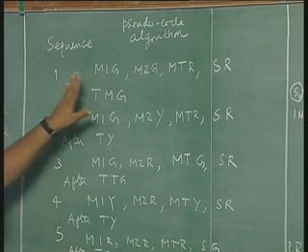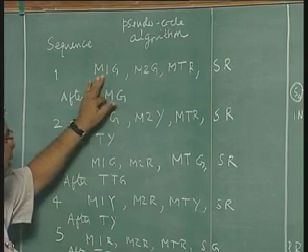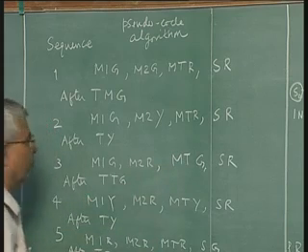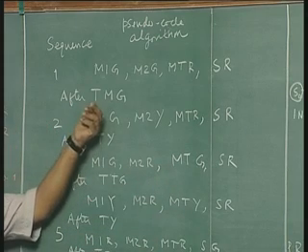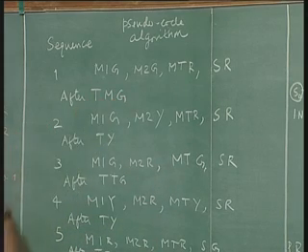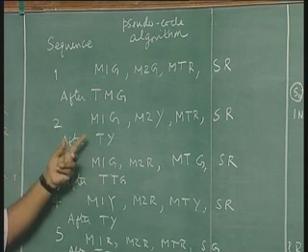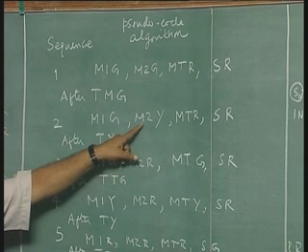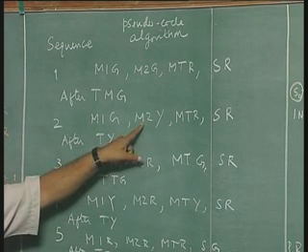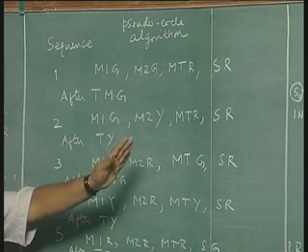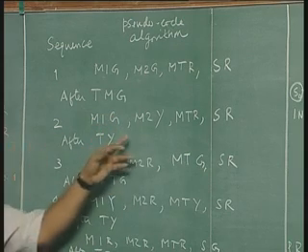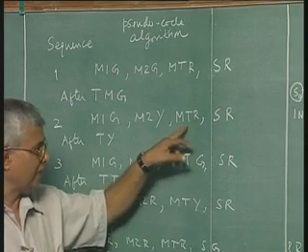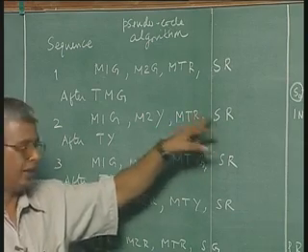Normally the circuit is with main 1 green, main 2 green, main turn red, side red. This condition allows for a period called TMG, main green time. At the end of main green time, M1 continues to be green, M2 turns yellow to start stopping the traffic from right to left on the main state. MTR, the turn signal, is still red, and the side signal is still red.